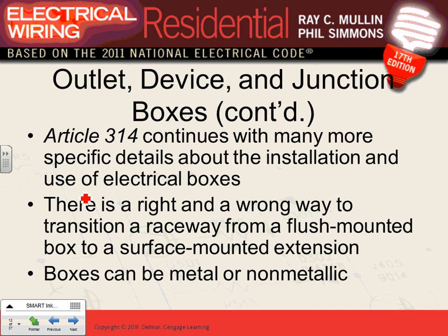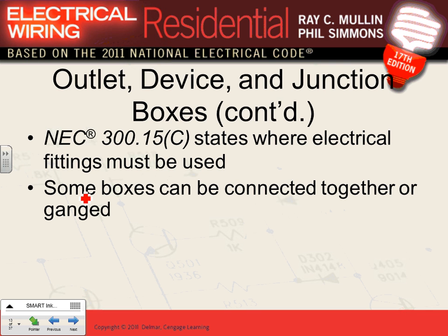Okay, so we talked about boxes, guys. Boxes, they can be metallic. Now you talk about here industrial, commercial. Non-metallic, typically residential. So we're right in here, non-metallic boxes. You're familiar with that one. That's most of what we're going to be doing. Metallic mainly is going to be in industrial.